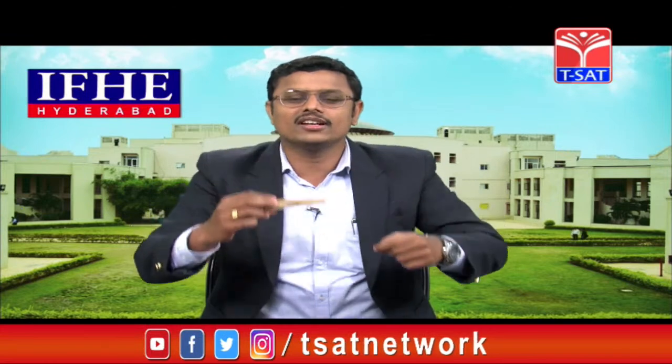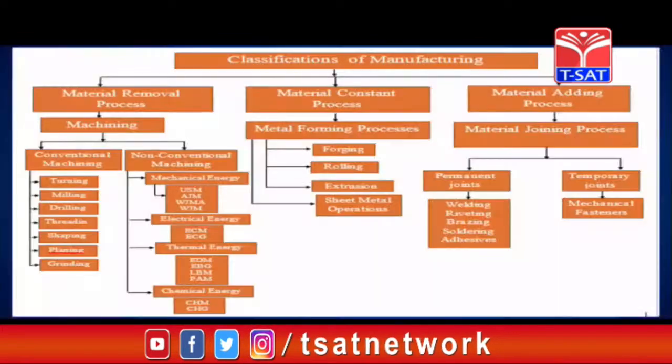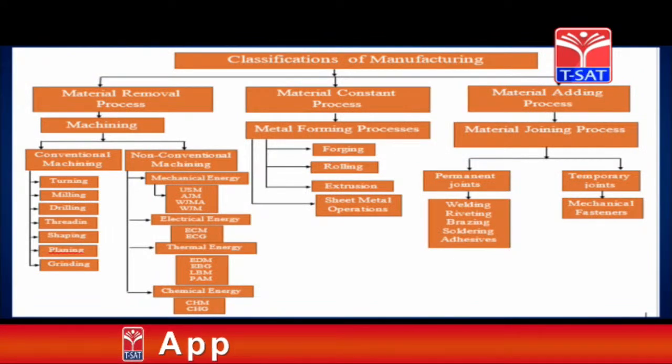Then how are we removing, sir? The tool is not touching and the tool is not harder than the workpiece. How are we removing the unwanted material? We are using different energies. What are those energies? Mechanical energy, electrical energy, thermal energy, chemical energy, etc. In mechanical energy, there are multiple processes like abrasive jet machining, water jet machining, water abrasive jet machining. And electrical, there is electrochemical machining.